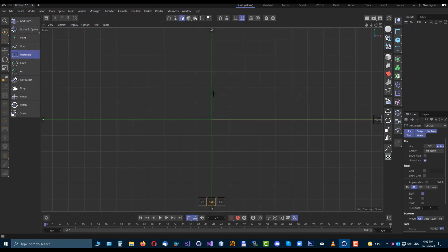These tools are designed for speed modeling. So you have to first understand how to use them, then you will be working really fast. So when you activate the tool, then after the first right mouse click you end the phase of this tool, and you can start again with the same tool. So again, create another rectangle.